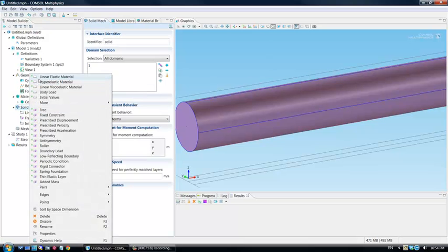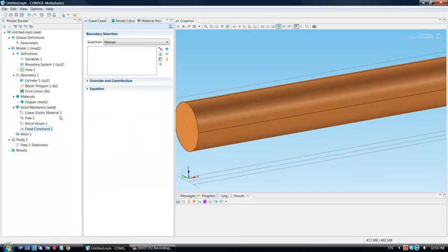So here again, the white represents body forces, while these bottom sections here represent boundary conditions, and you can also add point constraints as well, which is under this tab here. So I'll be adding a fixed constraint. I'll choose this face here, and I'll right click to add it. So that will now be a fixed constraint, meaning that the displacement field will be 0.